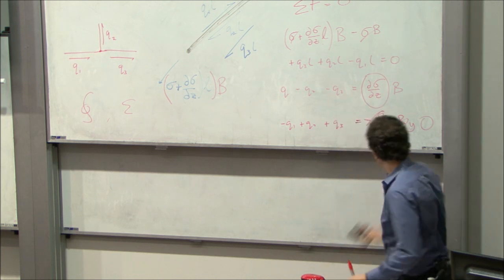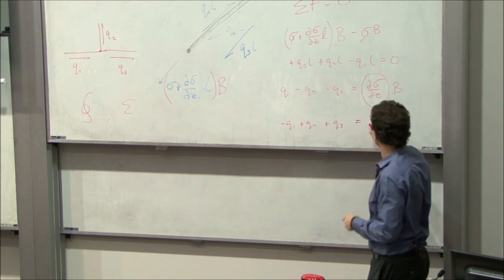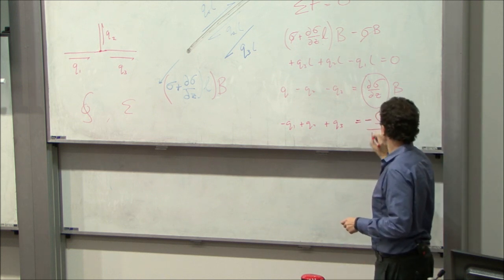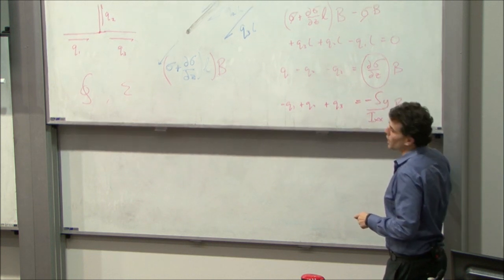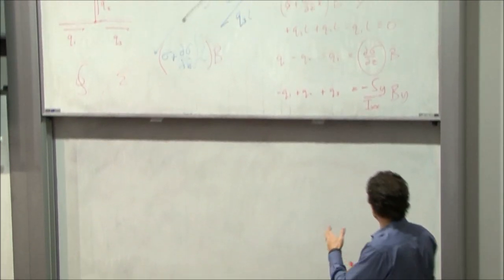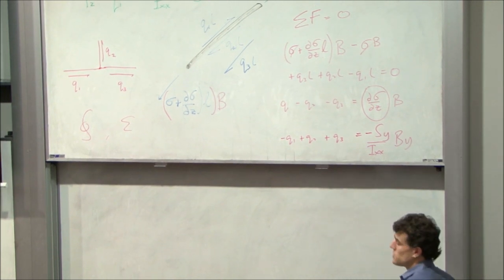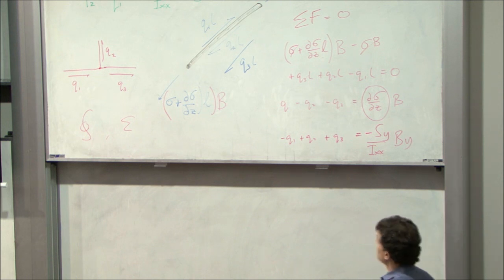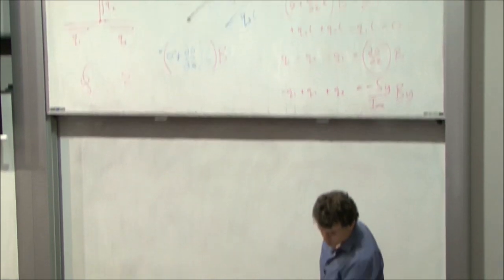Once we put the idealized boom area in, we need to make some slight modifications to account for the force in the boom. But this gives us the ability to handle intersections in our problems. A lot of problems we can cut in such a way that intersections aren't that problematic, but we can't always. So I'll show you an example of how this is applied.